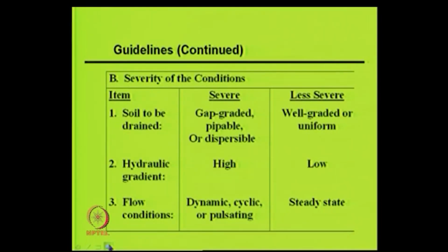Then what are the other issues that we have? One is that it is also a function of the type of soil. If the soil is gap graded, okay, or pipeable, pipeable means that it can easily come out, or dispersible. If the material is well graded, then the problems with filtration are less, because the distribution of particles is so well presented in that material that there is no problem of pore pressure mobilization and all that.